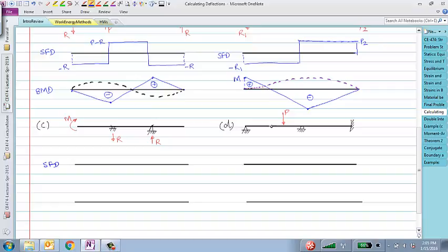What should the shear force diagram be? Starting with, go ahead. Okay, so which means that through this length and through this length, it should be 0, right? So we'll do that. 0 out here. Actually, I'll draw a solid line. Drop down to minus R. Be constant minus R. Go back up and be 0 throughout here.